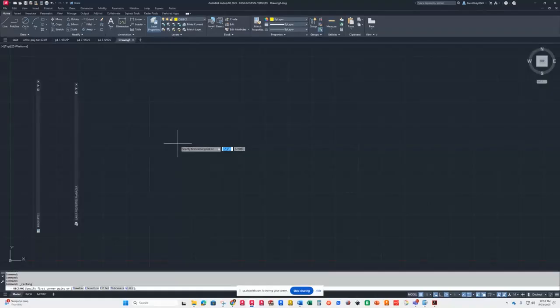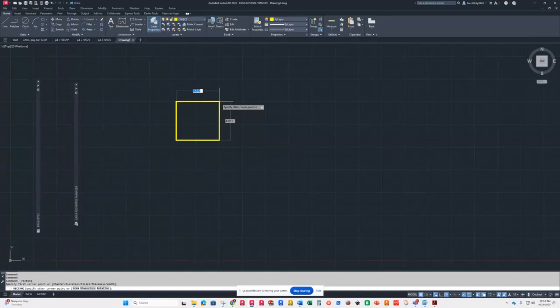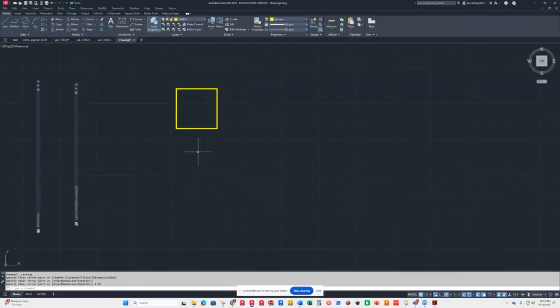And by the way, this one's going to have a right side view, because left and right side would be the same. So we're going to draw a right side view. So I could draw my top view up here like this. And you've got options of either typing in the relative other corner, or you could type in 2.75 and then hit your tab command. That'll take you over to the other dimension, which is 2.75, and hit enter. Alrighty.